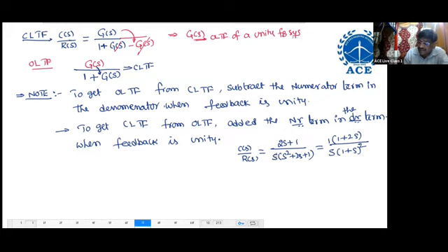After taking S terms common, whatever the constant is there, that you have to consider as denominator constant. Or simply adjust into time constant form. Whatever the constant is there, that is called system gain. So DC gain means simply S equal to 0. That means here DC gain is infinity. System gain means 1 here. Okay.